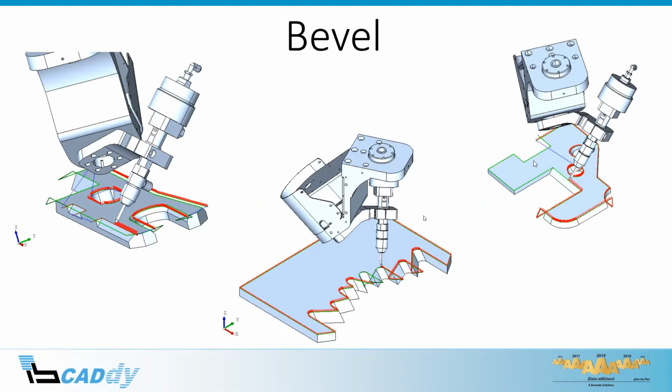From design to production, SigmaNEST makes the beveling process intuitive. As your parts are nested, beveled edges are taken into consideration automatically, and nests are optimized around the cutting tolerance required to produce accurate edge bevels. In addition to automatic bevel transitions, SigmaNEST gives a visual update to allow the operator to double check quality in real time.